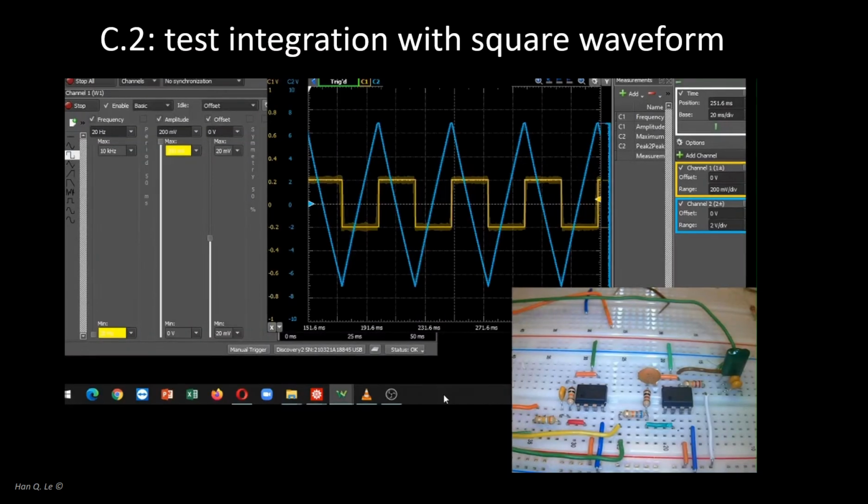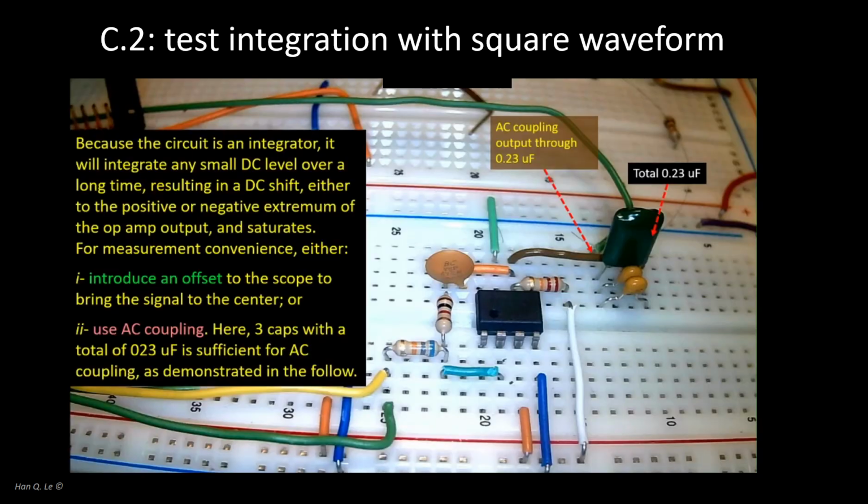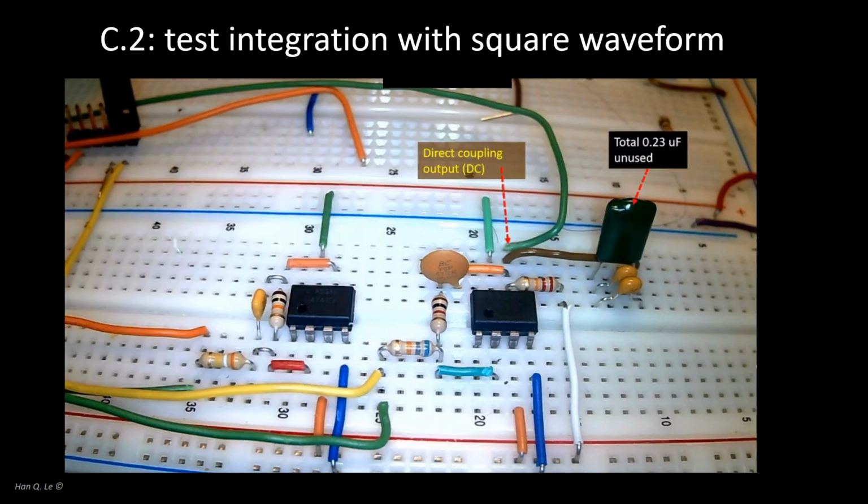This video shows the result of the square wave input test. It is meant to be a self-standing video. For the sake of self-containment, the use of AC output coupling is explained. The experiment was arranged such that the output waveform before and after the capacitors could be checked. The objective was to observe for any waveform distortion of the integrator AC component as a result of the capacitive coupling.